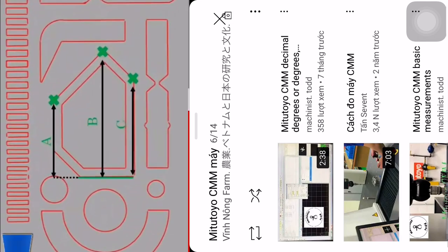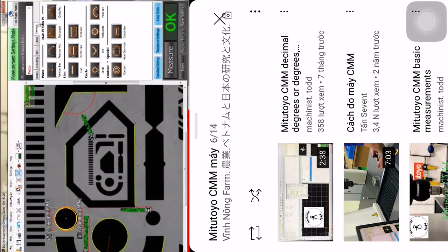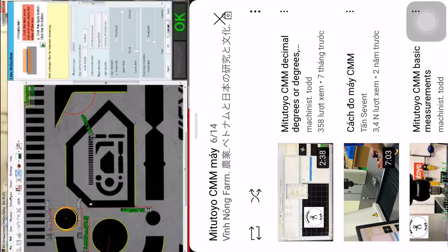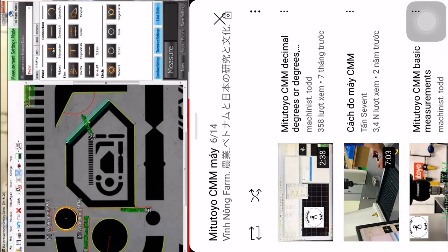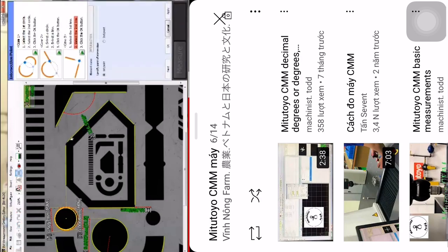Find A, B, and C, these intersection points. Under our Elements, we're first going to define all the lines of our actual polygon. Once we have the lines all in place, we can go under Virtual Figures, Intersection, and create the actual intersection points of each of those locations. Click Next to repeat the tool.